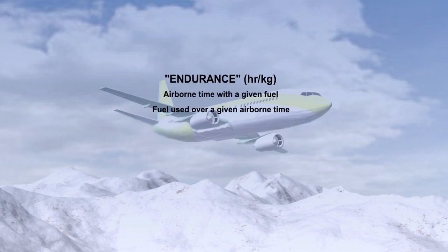The endurance of an aeroplane is the time it can remain airborne on a given quantity of fuel, or, put another way, endurance can be expressed as fuel used over a given airborne time. The only time an aeroplane will be flown by the pilot for maximum endurance is when the aeroplane is in a holding pattern over its destination. For instance, when there are long landing delays. In this situation, running out of fuel starts to become a problem.